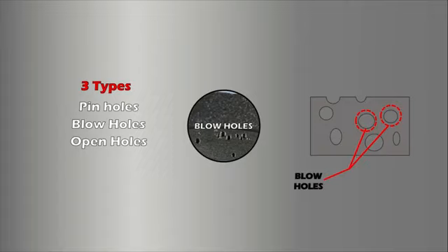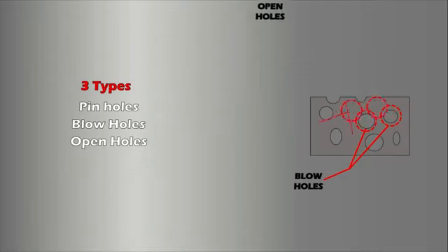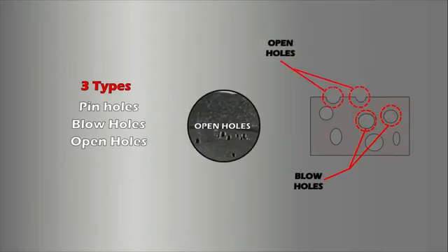Blowholes. Blowholes are larger holes that can appear on the inside of a cast piece. Invisible to the naked eye, interior blowholes are detectable by X-ray, harmonic, ultrasonic, or magnetic analysis. Open holes. A type of blowhole, open holes appear at the surface of the part. These defects are caused by air getting trapped as metal is poured into the mold.